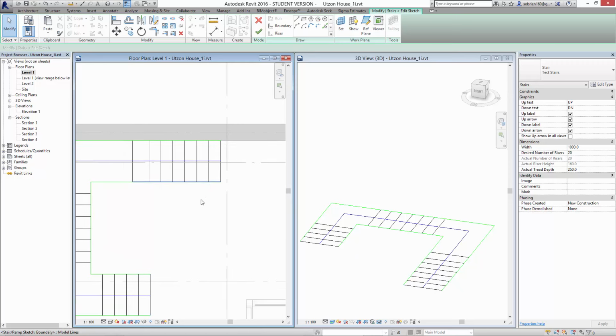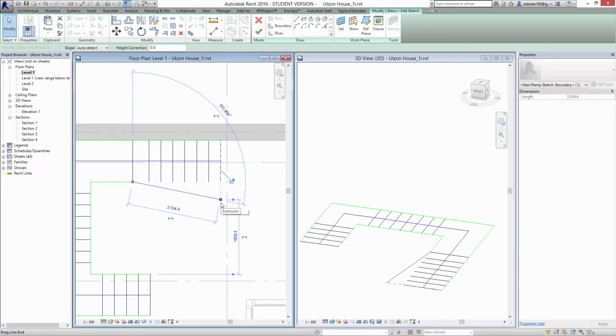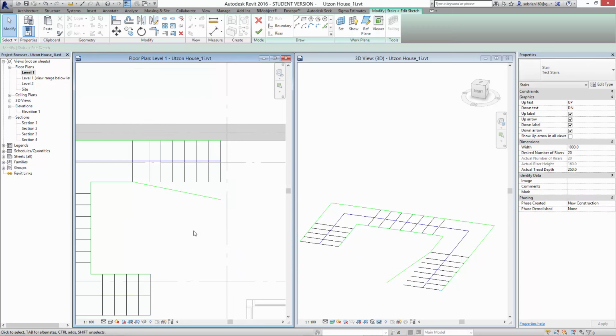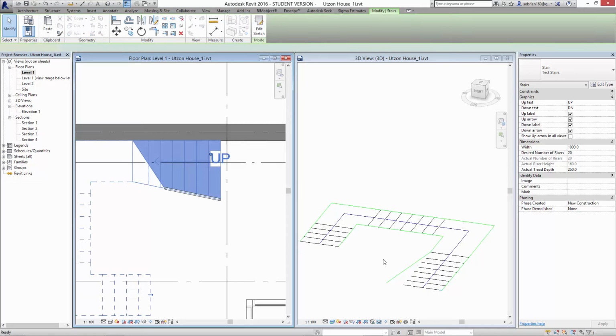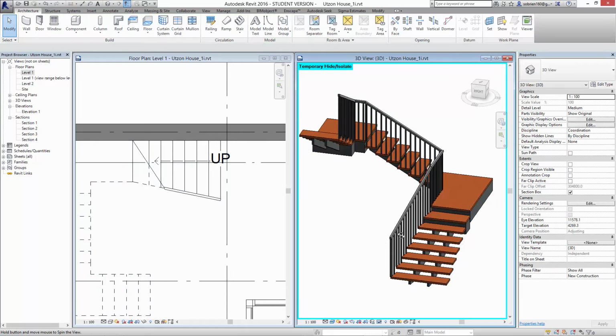So I'm going to make the front of the stairs kind of fan out, so you can come down there in your evening dress and look impressive. So I'm going to make it fan out. Just by moving the boundary, I can change the shape of the stairs by doing that very simply. And suddenly the stairs now has a kind of a fan to the front of it. Okay? So that's the first thing we can do.